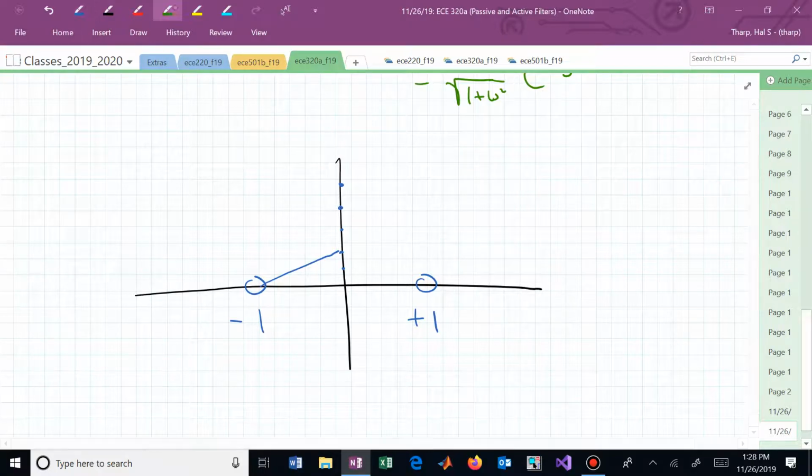And if I looked in the right half plane, I would be looking at that hypotenuse. How do the magnitudes compare between the two different zeros? They're the same, aren't they? So whether we have a 0 or pole in the left half plane versus the right half plane, their magnitude response is going to look the same. It's in the phase response that it's different.